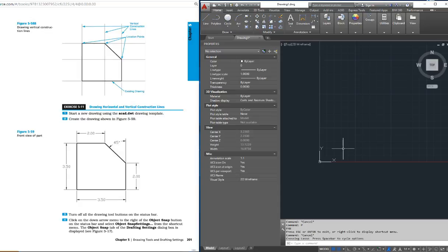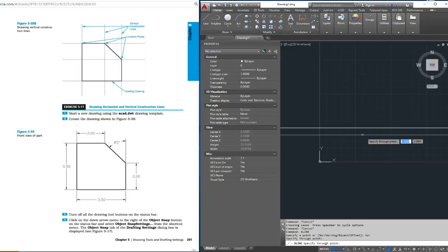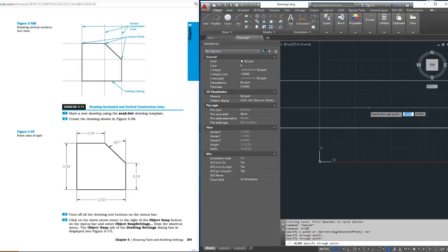So now, I'm going to draw this right here. I'm going to use the X line, and I get some choices down here at the bottom of the screen. What do I want to do? I want a horizontal X line. I'm just going to place that right here on that major grid line. Click. Okay. And then it says it's 3.5 inches tall, so let me just count. 1/2, 1, 1.5, 2, 2.5, 3, 3.5 inches.